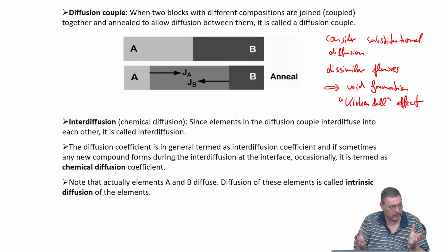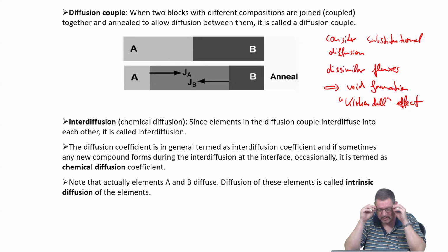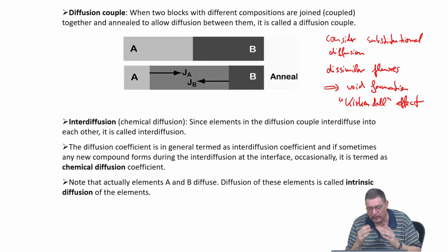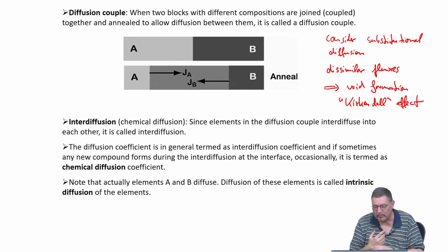And then if you have diffusion processes, Kirkendall voids are almost not to prevent. And that obviously is a stress concentrator and failure mechanism. For the diffusion studies itself, this is important because sometimes one can use these Kirkendall voids as markers of the original plane where the materials have been joined. But that's another story.